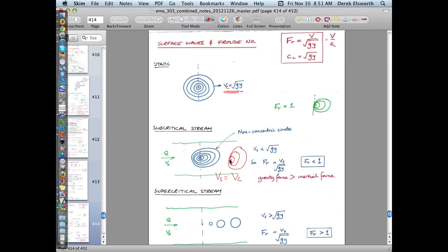And so what's happening here is, if you think of this in the same way, the information coming from the fact that you've dropped this pebble never reaches upstream. There's no communication. The upstream portion of the river doesn't know anything about what you're doing because there's no information transmitted upstream by a wave being able to travel there. And so the magnitude of the Froude number, which is the ratio of the velocity of the stream relative to the wave speed, when it's equal to 1, it's right on this verge that there's no information that goes upstream from the point that you drop this in.